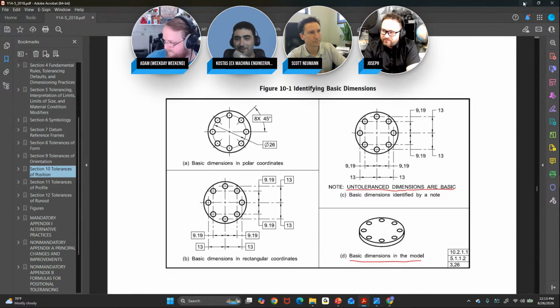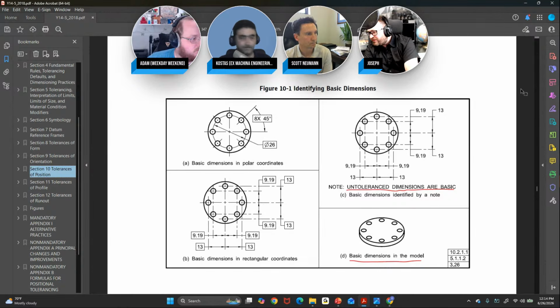And can I just say for our LibreCAD users that if you make a single hole and then do a circular pattern of it, you will automatically get the bolt circle showing in your drawing. That's just a CAD use thing, if you're so inclined. Whereas if you pop in the individual holes, you can still draw the bolt circle, but you won't get it automatically. Yep. Good opinion question on this one, I think.